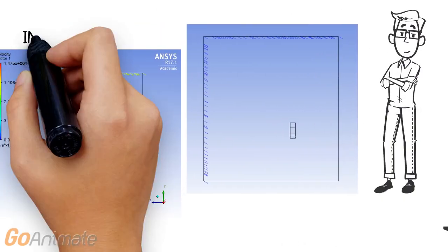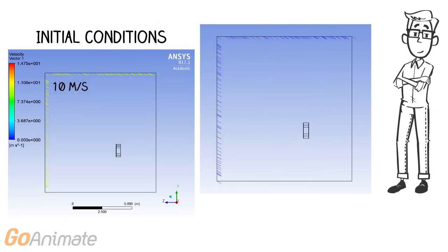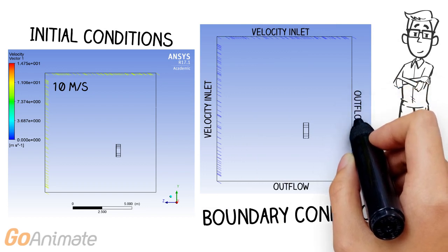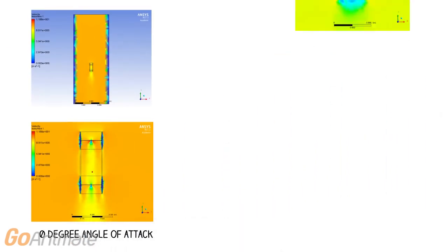The initial velocity was set to 10 meters per second and either entered at the angle shown for the 60-degree angle of attack, or, for the 0-degree angle of attack, the flow entered perpendicular to the y-axis. For the boundary conditions, the positive y and z axis were set as velocity inlets and the negative y and z axis were set as outflows. The analysis was run for 500 iterations.